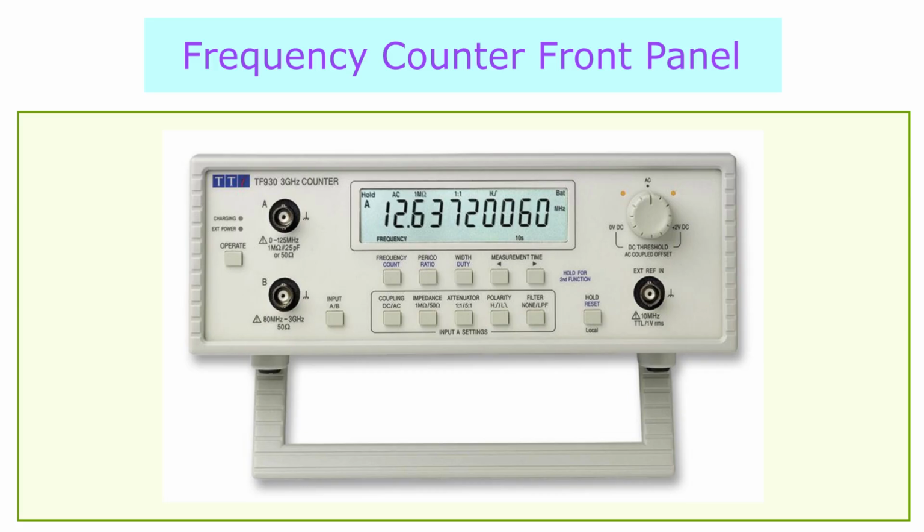The accuracy of a frequency counter is dependent on the stability of its time base. The time base stability may be degraded by vibration, electromagnetic interference, drift due to age, and temperature variations, thus making the measured frequency displayed higher or lower than the actual value.